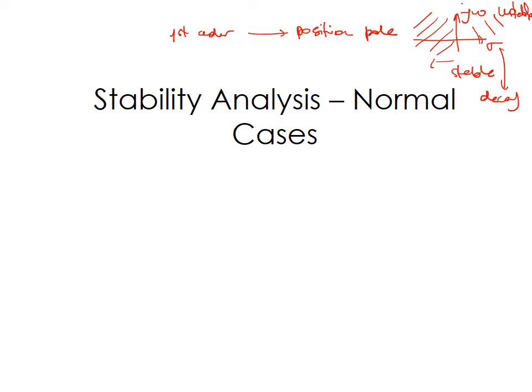Why? Because sigma represents what we call decay. If the decay is positive, it means exponential. Decay means exponential response. If the exponential response is positive, it means on this side you have a response that keeps on growing. But if you have a negative decay, it means your response goes towards a certain finite value and not to infinity. So for first order it is straightforward.